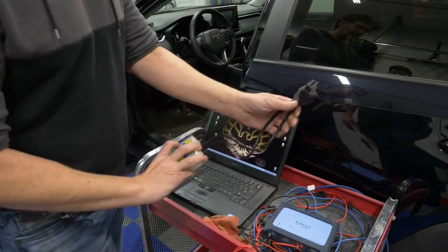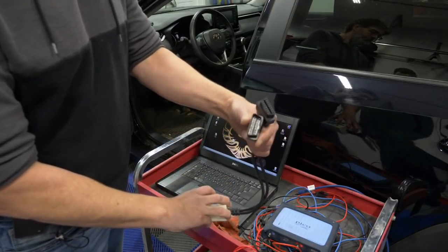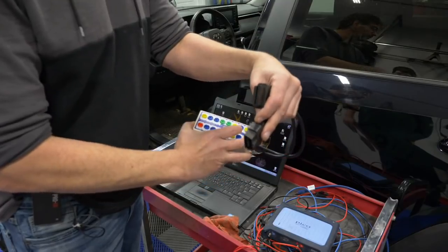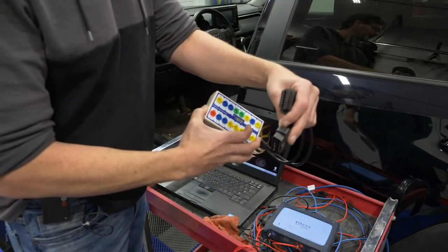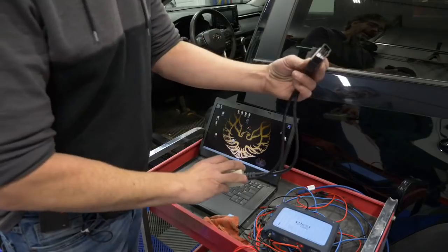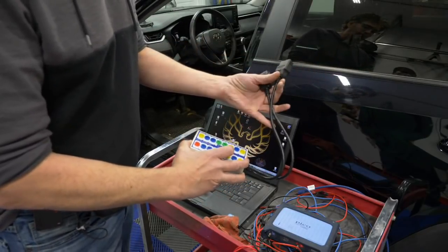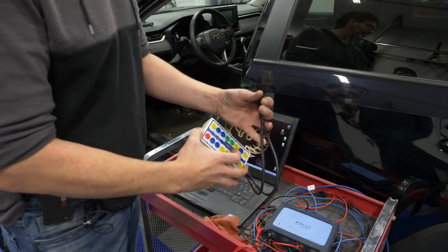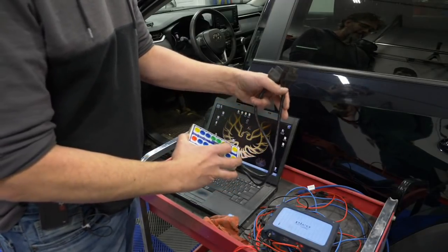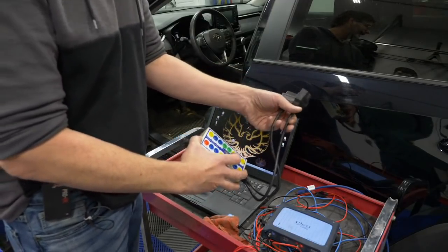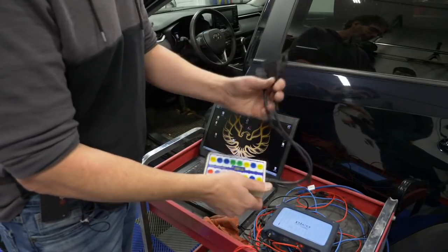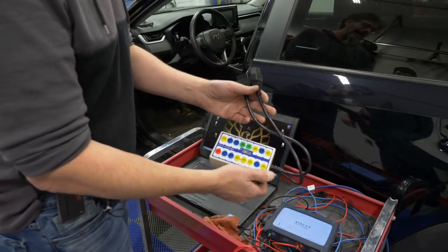The other thing you'll notice, I got this one because it has another port where I can also connect my scan tool to it, so I can use my scope and my scan tool at the same time. And based on what Chad's saying, this will be even more useful because now I can use my scan tool to make bidirectional commands and probably change some coding that we would be able to see as a result, so I can look if a module isn't responding. So while this is not necessary, it's going to be highly recommended.